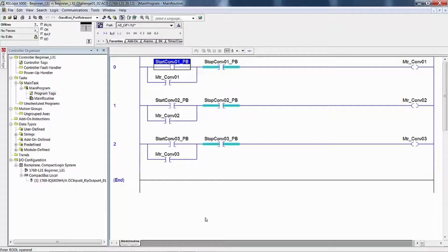And I'm telling you, even after you've done this a lot, you can still make that mistake. Oh, what a mess that makes. If you've got a big program and you've used a tag in, say, 10 different routines, and you accidentally edit it as part of other code and you don't notice it right away, oh my goodness, what a mess. Be very careful when you're messing around with tag names that you're conscious whether you're editing an existing tag because you want to give it a different name, not a new name, a different name.